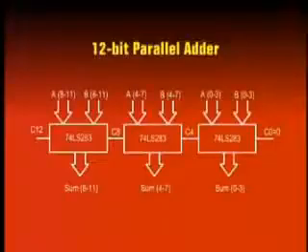Similarly, the 4-bit adder chip on the extreme right generates least significant sum outputs 0 to 3. The second 4-bit adder chip generates sum outputs for the bits 4 to 7. The third 4-bit adder chip on the extreme left generates the sum outputs for the most significant bits 8 to 11. The carry out is generated by the leftmost 4-bit adder. It is shown as C12. Similarly, the carry in is shown connected to the rightmost 4-bit adder. It is represented by C0.